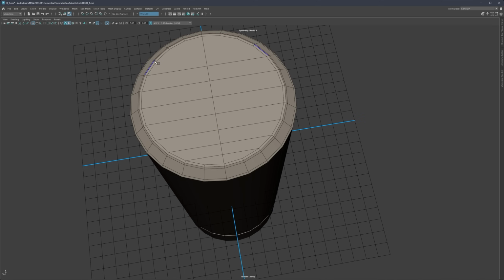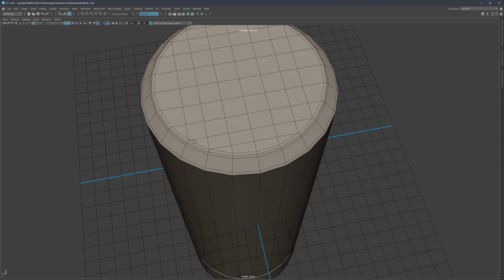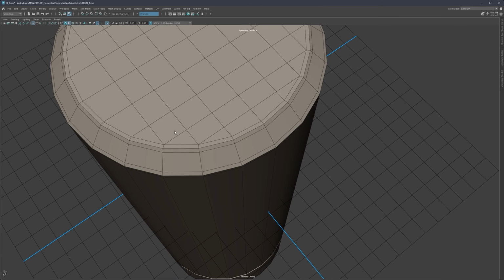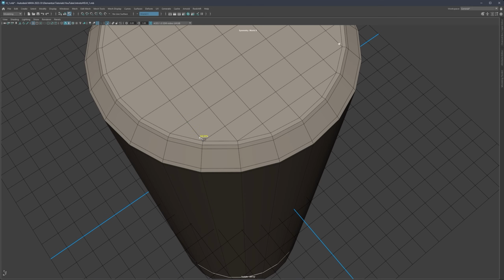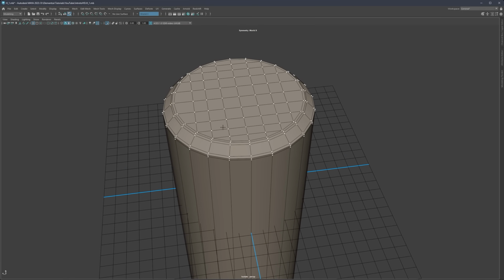You're probably going to notice that we're going to close a lot of stuff in triangles. So this is not a problem now. Let me just continue. So connect, right-click to confirm, and I think this is fine. It's not really that much of a problem that we connected in triangles, because later when we subdivide, triangles will get fixed, and if we want to get rid of the triangles, we can close them like this. But for now, I'm just going to leave them as they are.